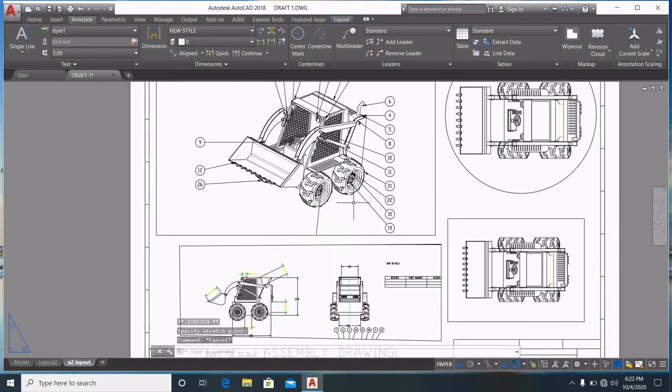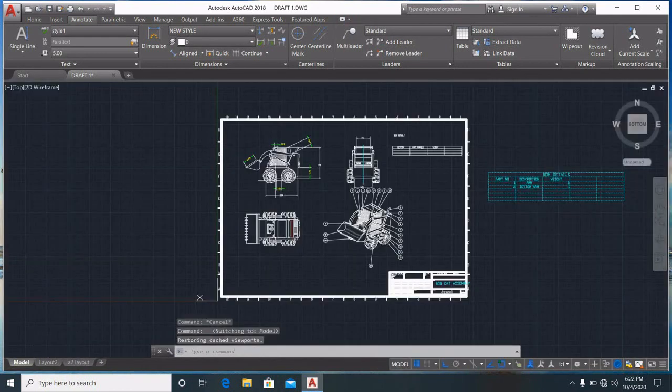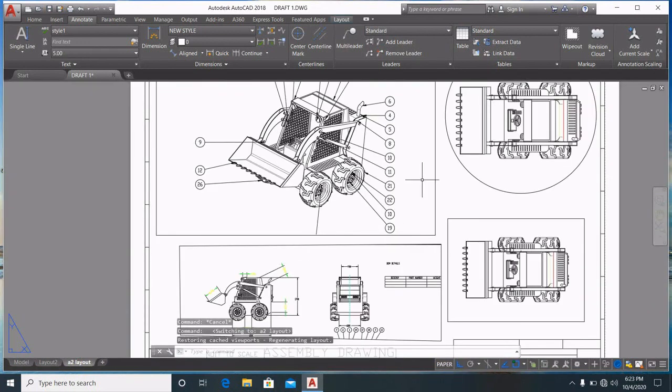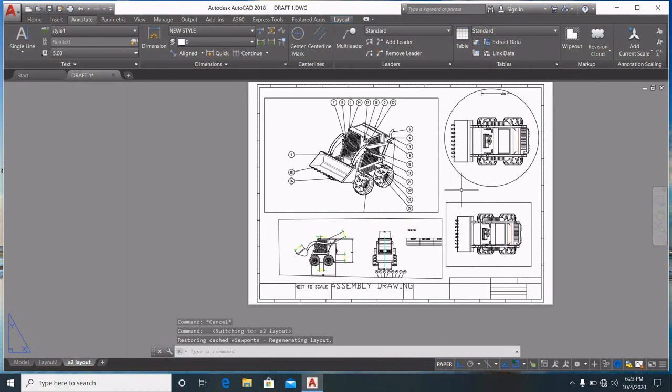In this way you have imported all the drawings from SolidWorks to AutoCAD and made some edits here. I have shown you how to edit here. You can also add some things like balloons, dimensions, many things. Then if you assemble it in an industrial way, you have to make it like that. You can place all types of drawings, one part, two parts in one frame and in an A2 sheet.